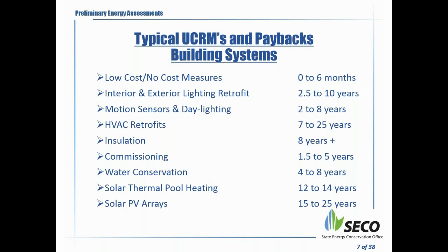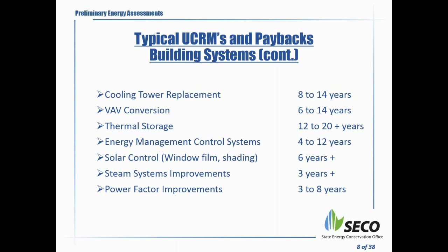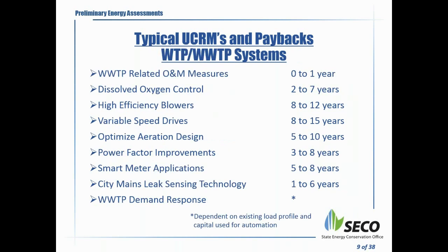So that's why you've got a wide range of paybacks, and that's something to keep in mind. You have a wide variety of paybacks for different measures, and that is one of the reasons you want to do an initial assessment or preliminary energy assessment, which will narrow this range down and give you some input on what kind of measures you're potentially going to have.